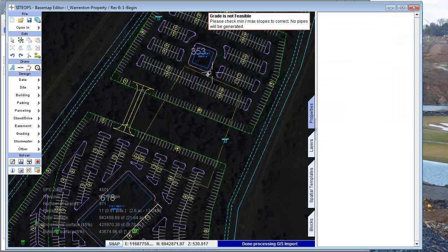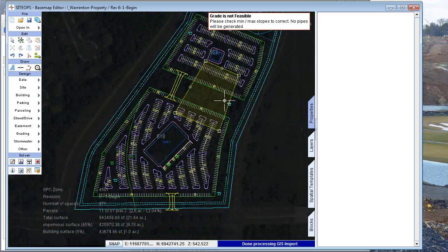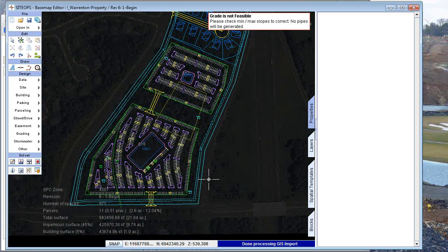Now, the idea here is that if it's unsuitable soil, it needs to be removed off the site. So it's going to have to cut down 3, 4, or 5 feet there to collect that unsuitable soil and then remove it off site, and there's a cost for that. But that leaves us with a big hole, and so the software knows that it has to backfill the hole, and then it has to put materials right on top because I've also encroached on 2 of the parking lots here, and so it's going to dig the hole out and remove it at a cost, backfill it in again, and then lay the parking lot materials on top. This is a very, very heady calculation, all being done within a matter of seconds.